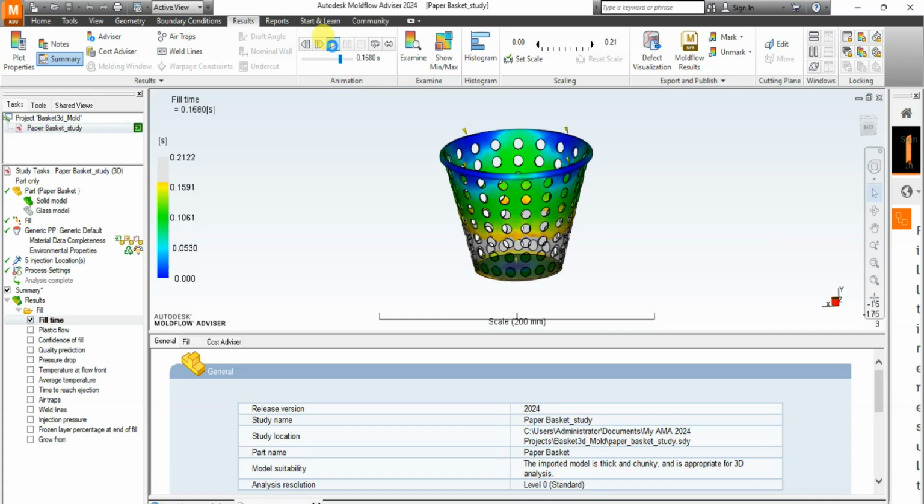It usually results in incomplete, defective products, and has translucent attributes in the simulation of the object in question. But in this case you can see that the translucent property is not present. We have an evenness here, so the flow pattern is balanced, and this indicates that the part we are dealing with has a very excellent fit for production.